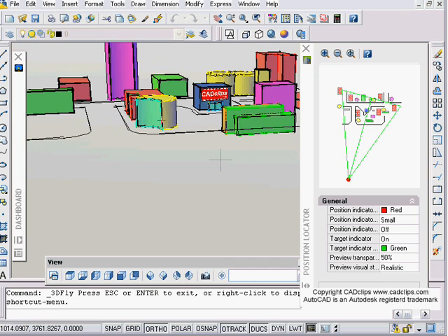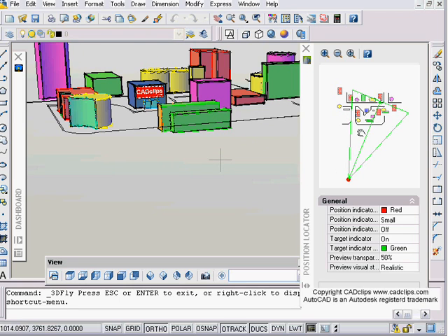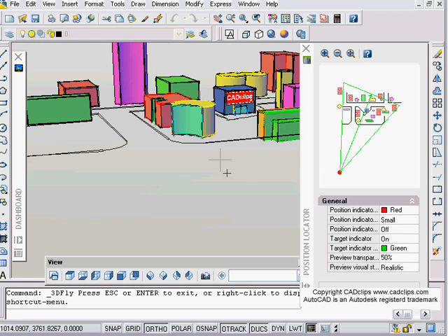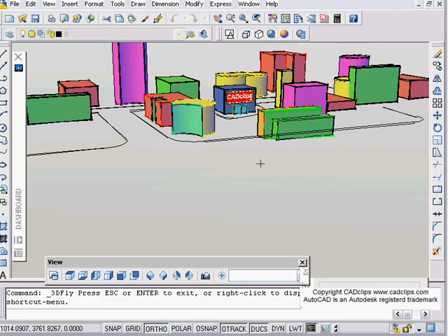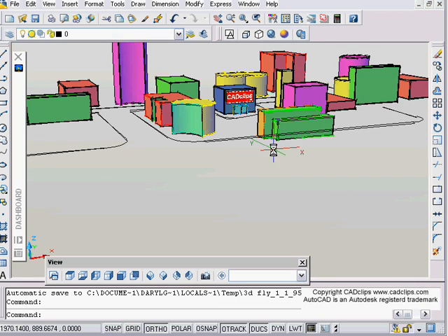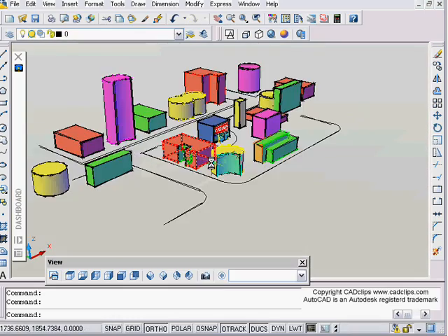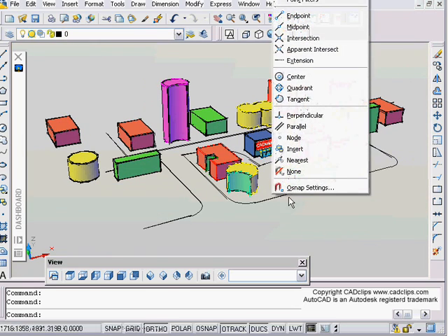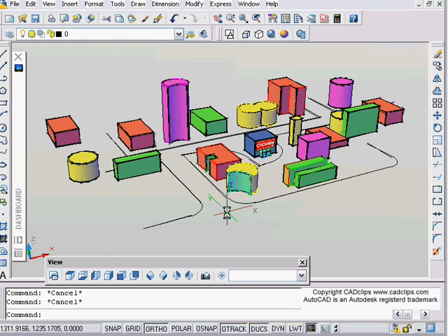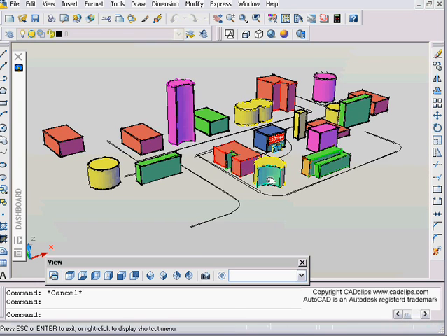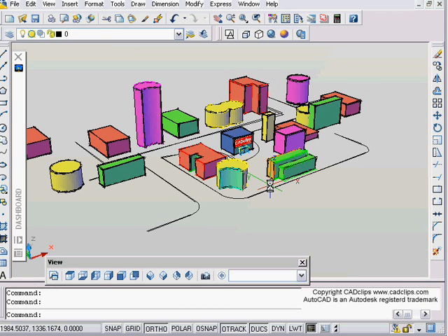Okay, and then remember again, using a mouse button over here. Again, you can take that and just move that if you want right on screen. Okay, and then sometimes, if things get all botched up, you just hit enter and it bumps you out and it leaves you in that view. Now I can use my normal pan command and my shift middle mouse button, maybe get myself in position, because it's going to take a bit of practice. Okay, and it really depends on the shape. The flyby is much better for the flying, for actually going through a path. To go through and turn around and come all the way back, I'm finding is a little bit tricky to do, but maybe over some practice I'll learn how to do that.